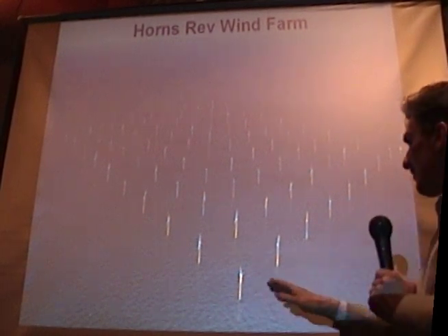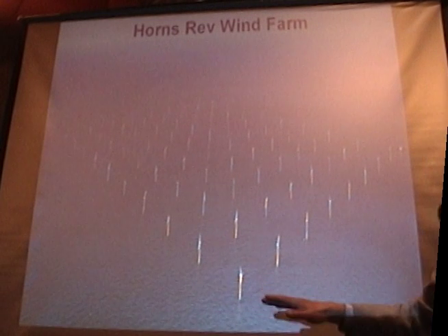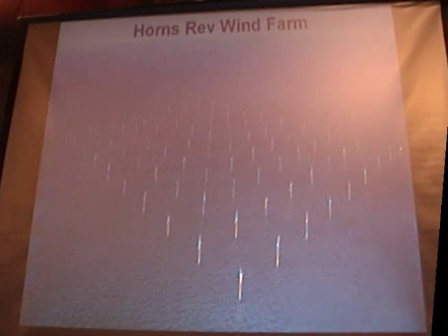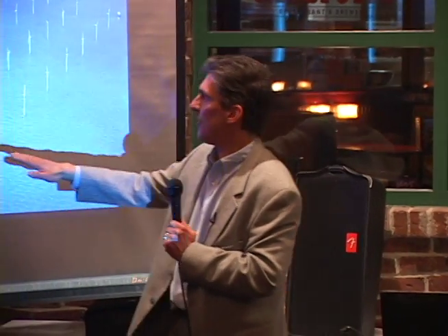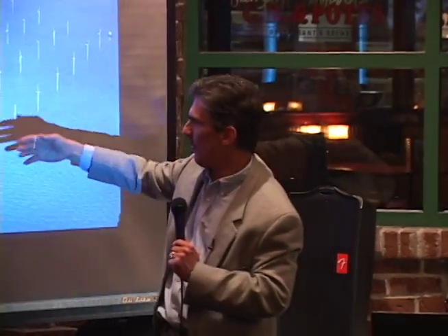So they're finding that there may be arrangements that can actually enhance the amount of energy that a wind farm can make. The bad news is that in the same condition, these turbines back here are doing really poorly in the back of the wind farm, because there's all this mechanically generated turbulence that comes through and disrupts the power production. So we're not done with array effects. We're just beginning, in fact.